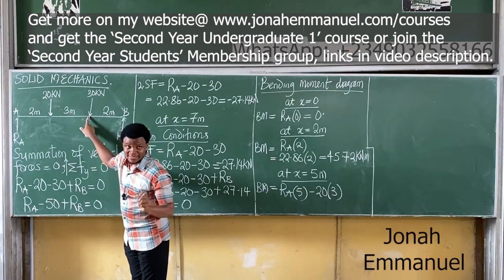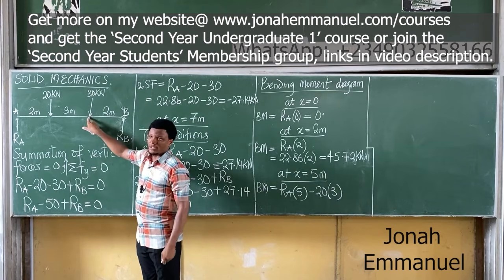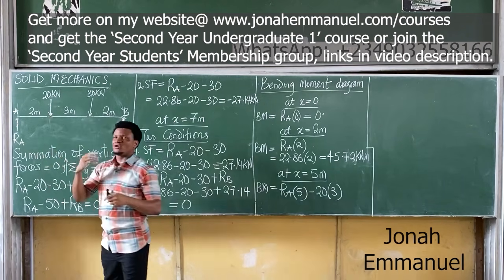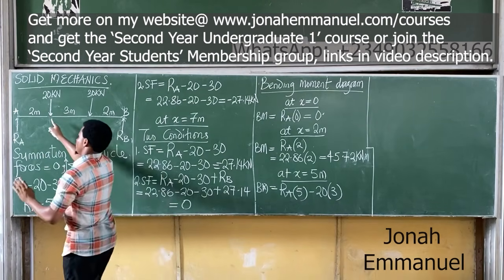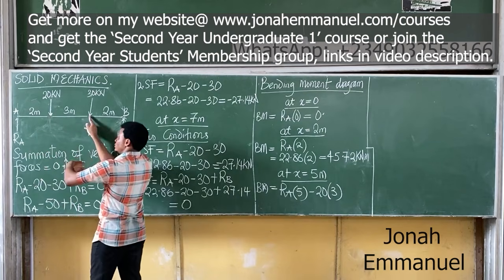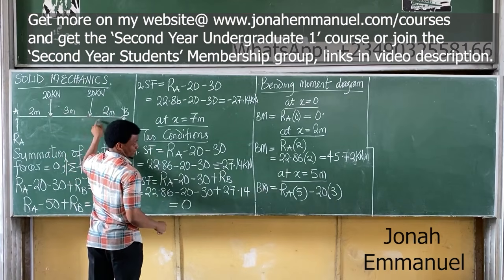We know why, so we are not going to start stressing why we omit the one at that point. Because this one becomes this times 0 at that point. So you omit it. What we did at x equal to 2, we used only RA. Look at it. When you're doing bending moment, you're only taking the forces before that point. That's all. Before this point, I had RA, so it was RA times 2. Come to 5, you use the 2 before that point. Clockwise times 5. Anti-clockwise, minus 20 times 3. That's all. You don't include the one there.